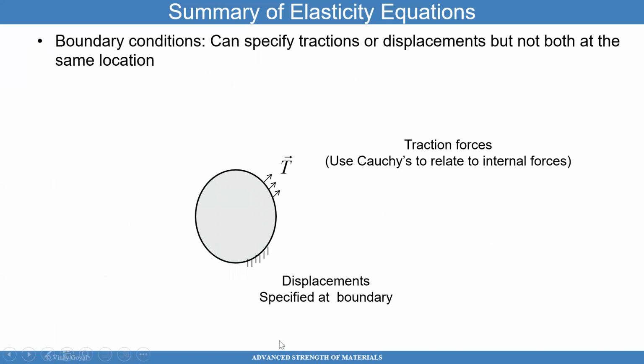We also have boundary conditions where tractions are applied on part of the surface, and then we have boundary conditions where you may have a fixed boundary, and with the loads applied on the fixed boundary, that's going to help us understand, along with the 15 equations and 15 unknowns, what the stress states are that are occurring within the body and whether the structure could fail catastrophically.